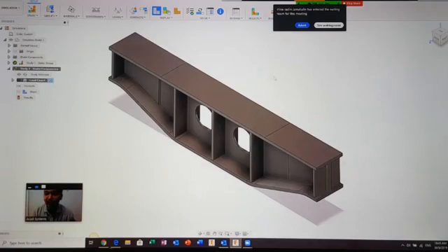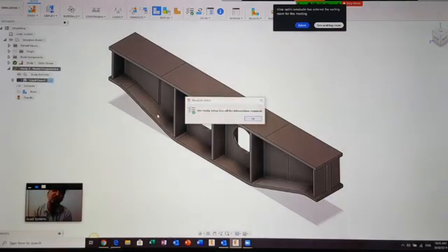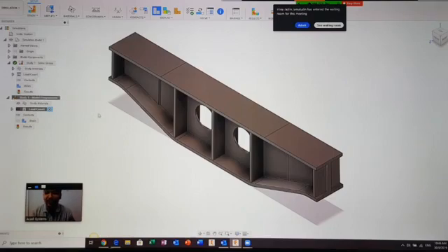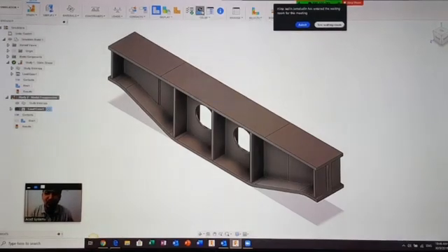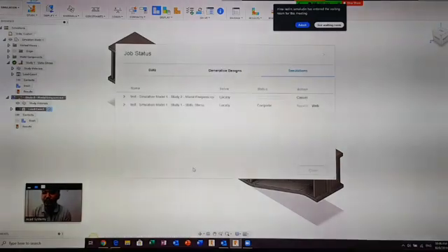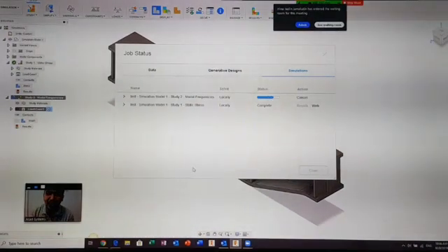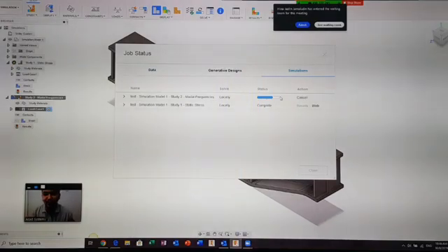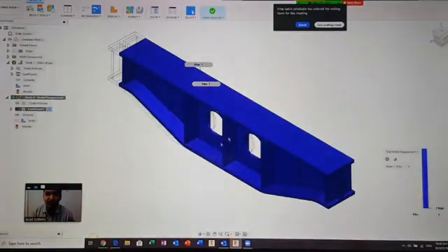I didn't do anything towards this. I didn't put the material, I didn't put the constraint, I didn't put the load. But when I check the study, it has all the information required. It means it remembers the load and material that you set earlier. So let's just click solve here, and again I'm using the local, and I click on solve. So now I have the second calculation for modal frequency. Let's wait a while until the calculation completes.